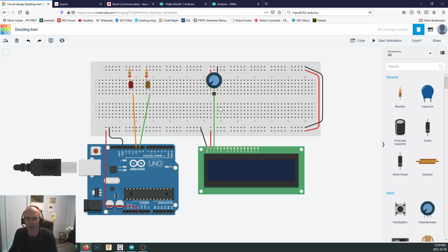Okay, so what happens is when we're displaying things on our LCD, if it's coming up too bright or too dim, we can adjust the contrast button. This is just like a little contrast dial that you'd have on an old black and white television or something like that. Okay, now that's got the first few pins set up for us. Now we're actually going to start making connections to our Arduino.